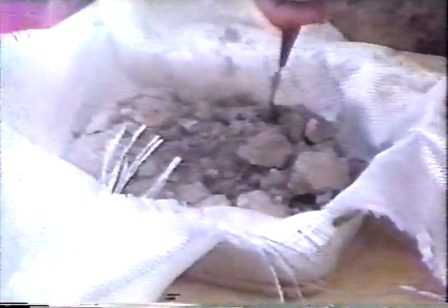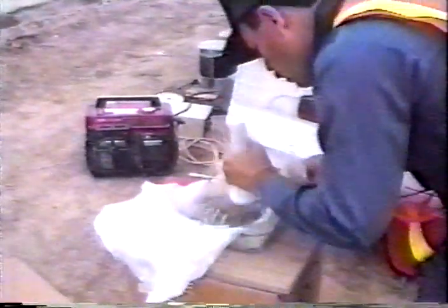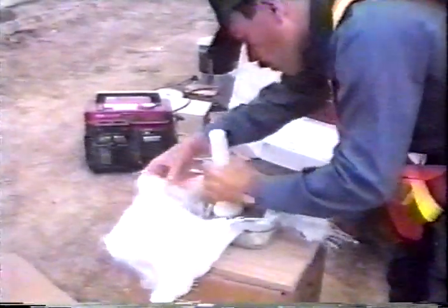With the edge of the scraper, the mass of concrete is broken until the coarse aggregate is separated from the mortar. Then, the mortar is ground with a pestle to expose more aggregate surface area. This helps the sample to dry. No more than 1 minute should be spent on the grinding, and care should be taken not to lose any material in the process.